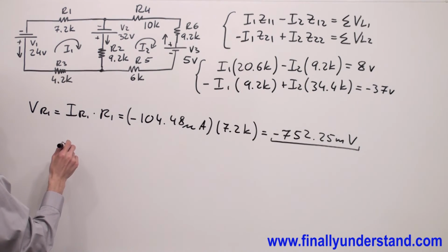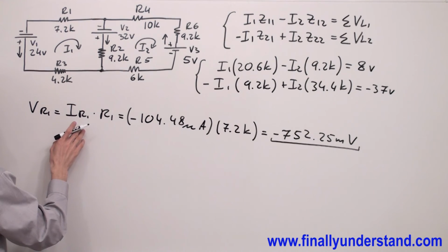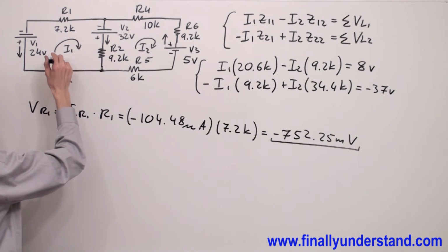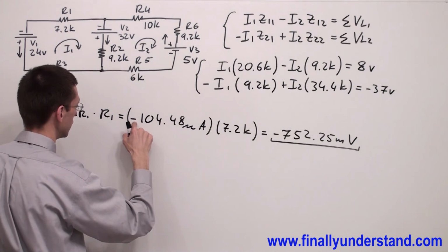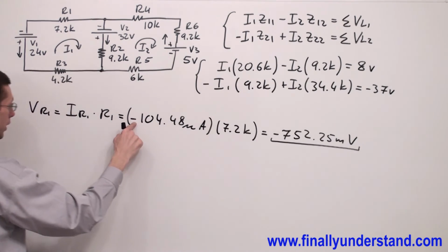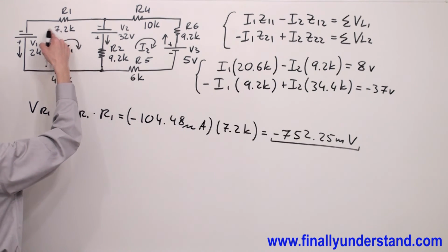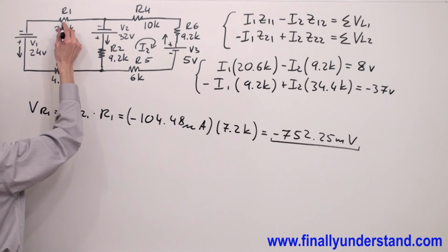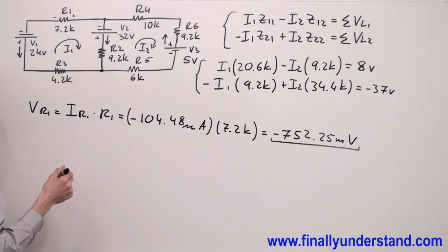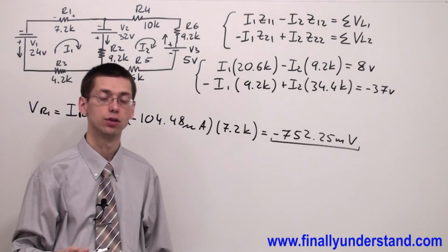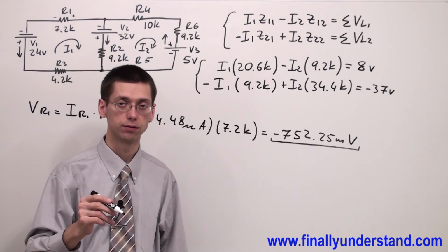Okay, so if someone is going to ask about the polarity across the resistor, please keep in mind that this is the current which we assume, and because I have a negative sign from my calculations, it means the real current will go counterclockwise, so the polarity across the resistor is going to be positive and negative. Remember, anytime current enters the component, you're supposed to write a positive sign.